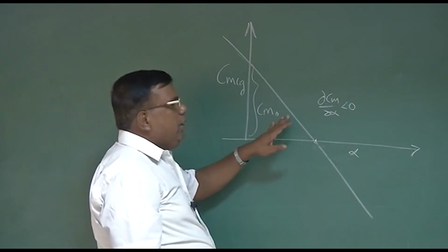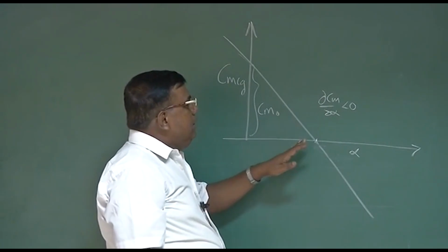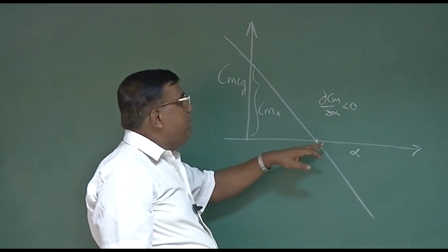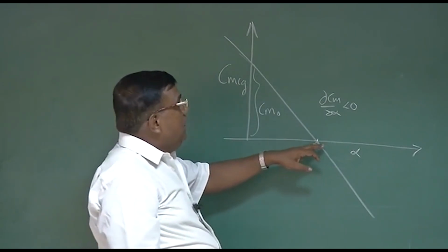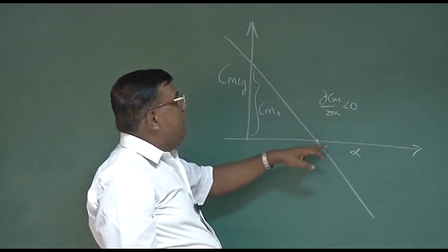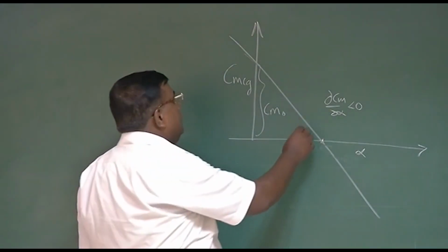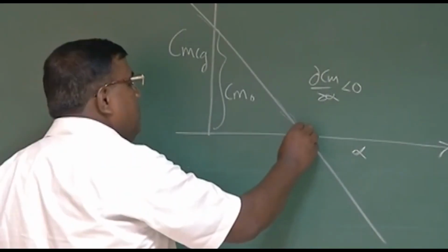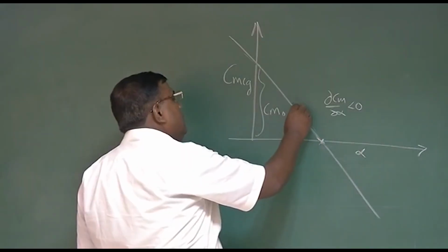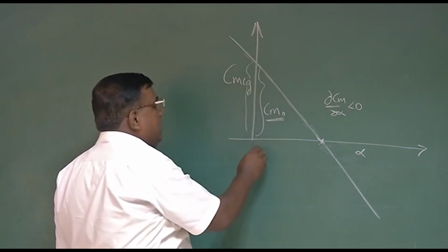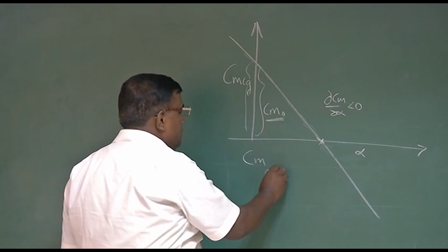And we know that for a statically stable airplane, I need to see the slope at the equilibrium. At this point, Cm is 0, and I have to check that dCm by d alpha is less than 0, so it's statically stable. Also, if I should trim at a positive alpha, then not only the slope, I should have a defined Cm naught, or Cm at alpha equal to 0.